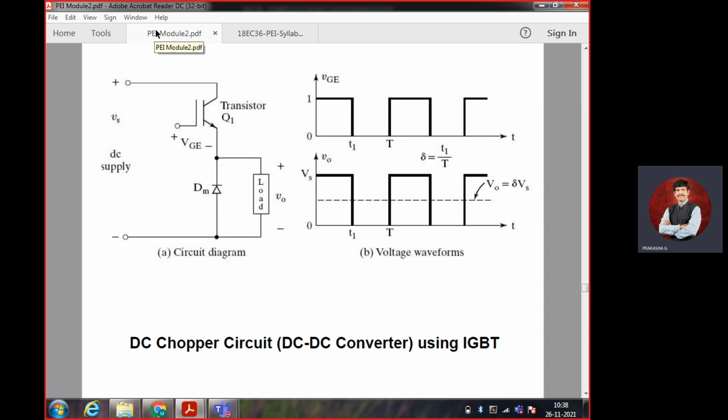That will be nullified. This diode we are using in the circuit, I have written as D or have not written anything, DF, freewheeling diode, we are going to call that one. This freewheeling diode will nullify the extra voltage which is generated by your load. Whether it is an inductor or capacitor, whichever device you have, it will be discharging, and the discharging can be nullified.